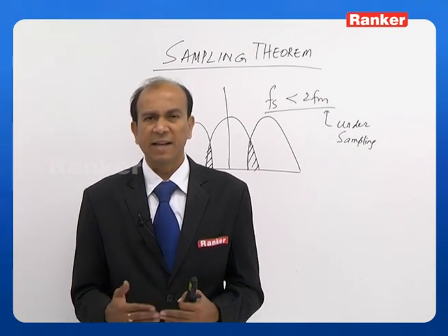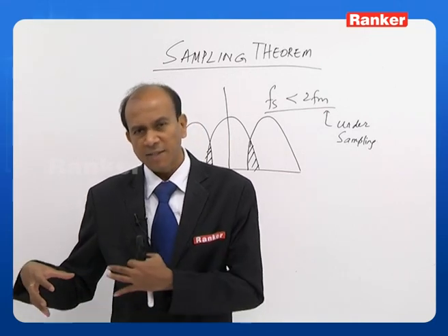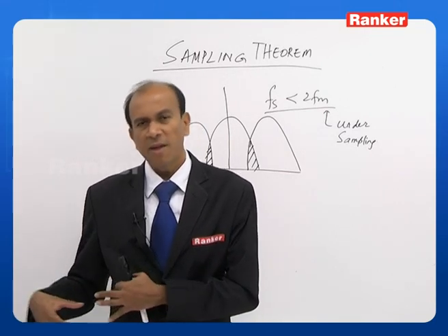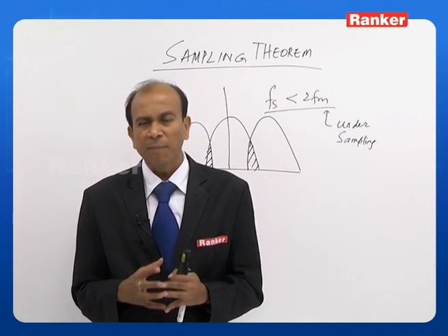These are called anti-aliasing. So, to avoid aliasing, use a pre-filter and increase the sampling rate to Fs greater than 2FM, and then you will get a signal which is free from aliasing.